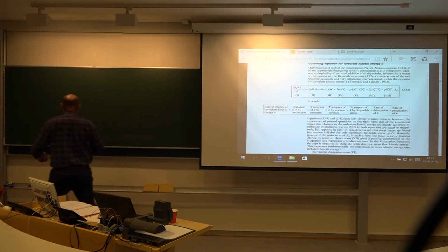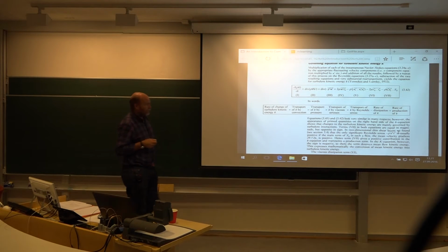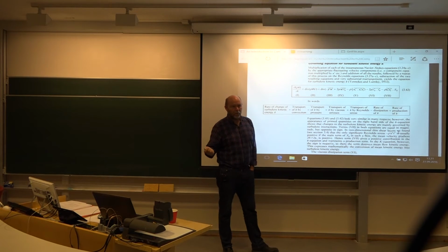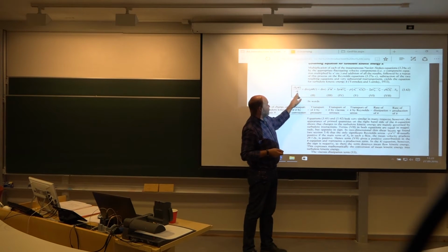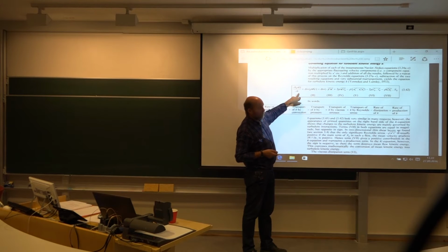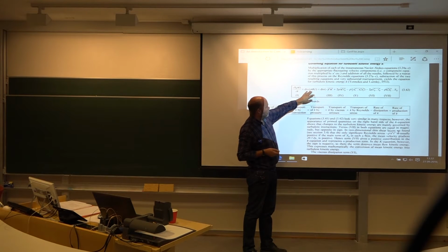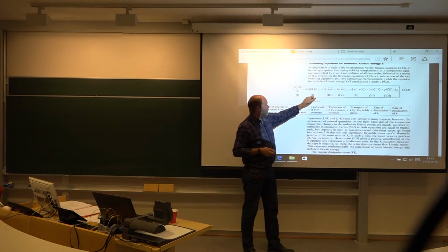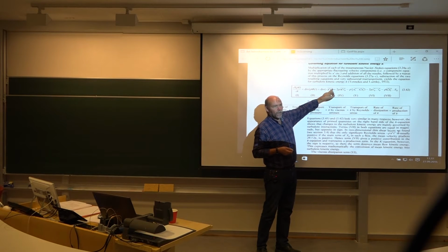And if you look into that equation a little bit in detail, you will be rather scared. I mean, if K is an unknown function, describe him, find him. The 2 first terms here are quite okay. You have the rate of change of the quantity, the time derivative, and then advective or convective acceleration terms. But then you have a whole bunch of nasty terms on the other side. What's this one? Here's the fluctuating pressure multiplied with a fluctuating velocity, and then time averaged. Thank you very much. What is this?